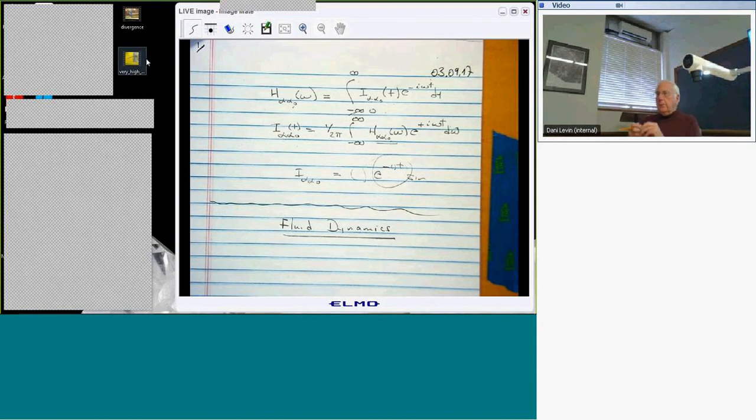Then you have to write down F equals MA, or as the fluid mechanicians would say, pressure acting, perhaps shear stress, but usually just pressure in classical aerodynamics, acting on the volume of fluid, and that gives rise to acceleration. But then often you want to write acceleration in the moving coordinate frame. We'll find out why a little bit later.